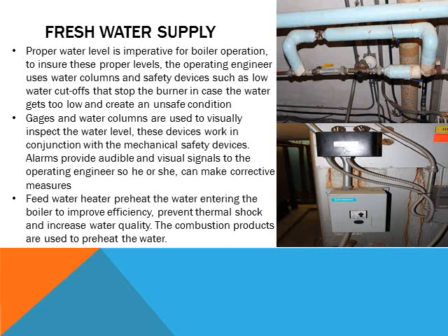Fresh water supply. Proper water level is imperative for boiler operation. To ensure these proper levels, the operating engineer uses water columns and safety devices such as low water cutoffs that stop the burner in case the water gets too low and create an unsafe condition.